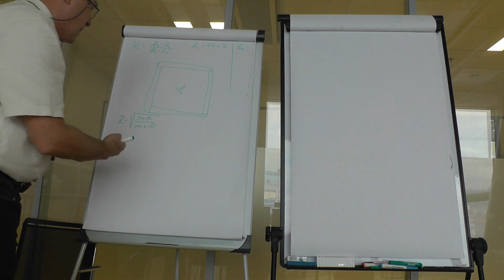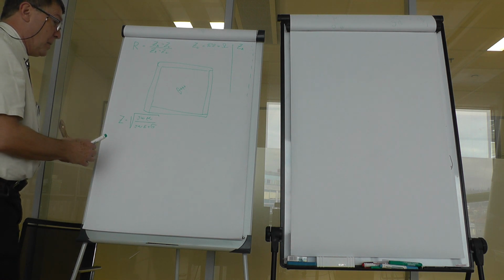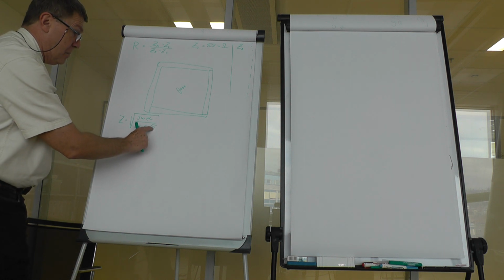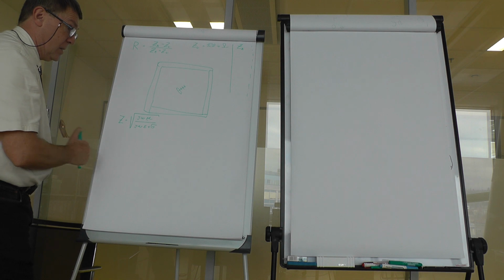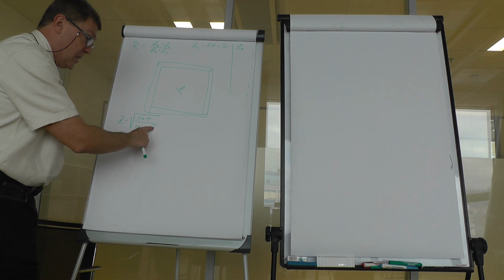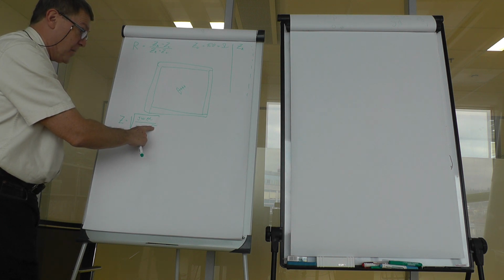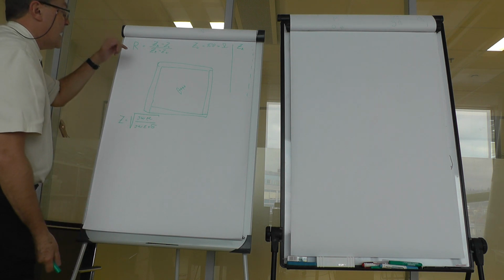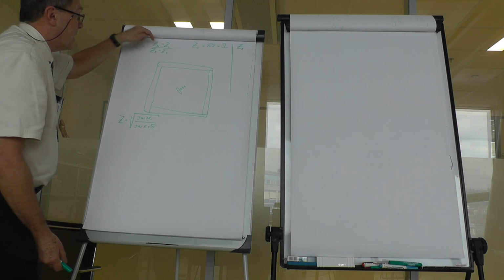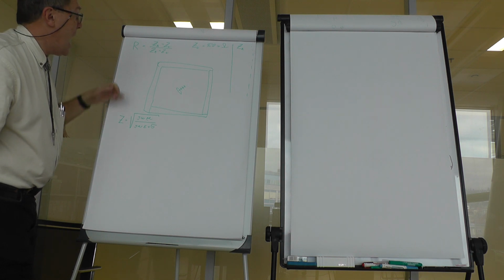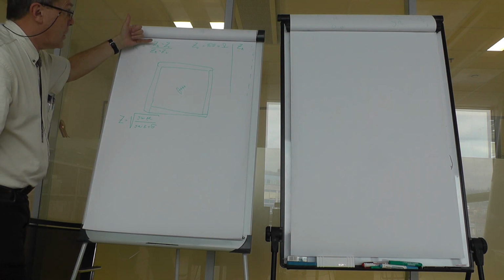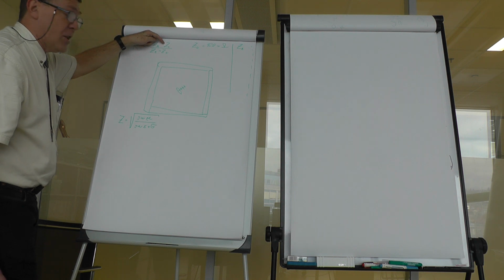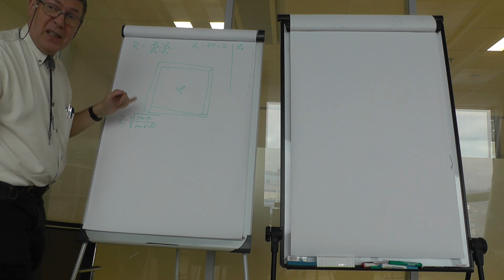Now the same we do in this numeric simulation. But the problem is that any material that should be lossy must be conductive. Conductivity is guilty for losses in dielectrics. So the problem is that once you get a lossy material, then the impedance of that material, ZA, is a complex number. And this ratio would never be zero because you have subtraction in the numerator and addition in the denominator.